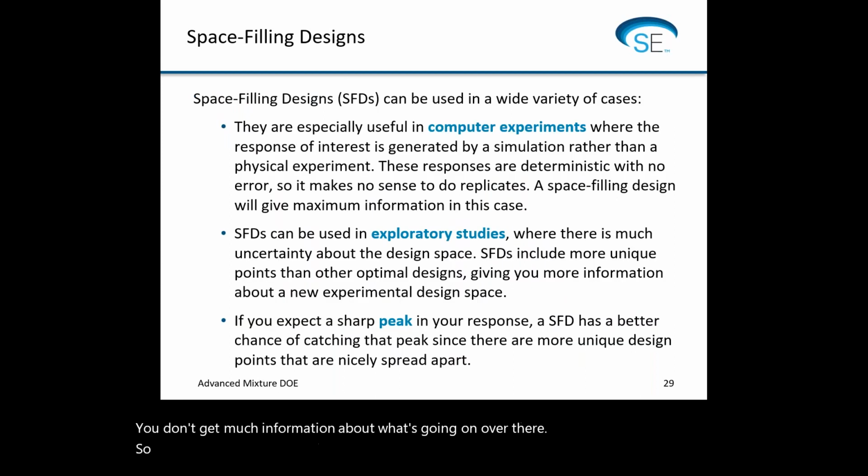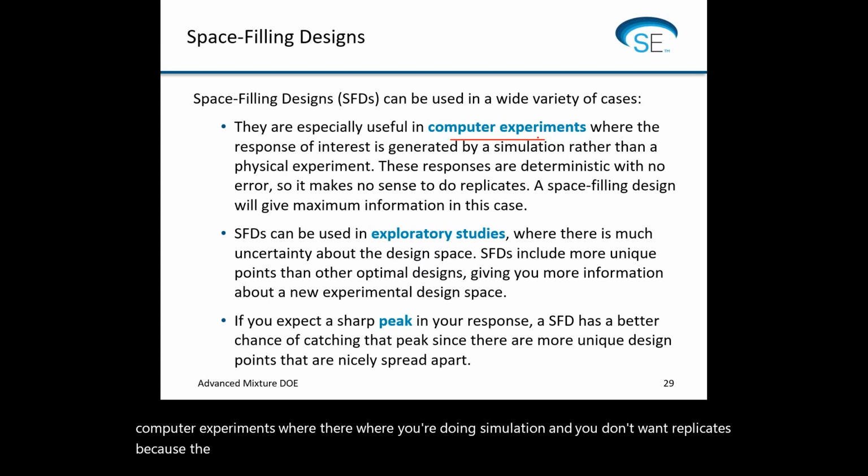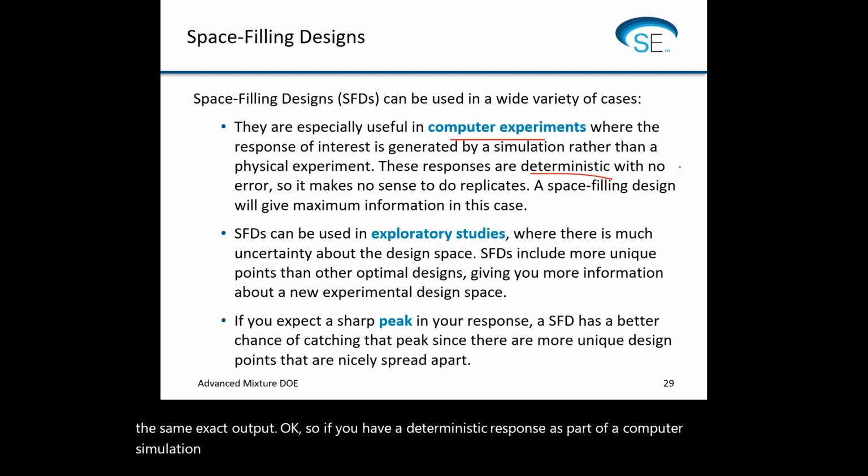So space filling designs can be used in a wide variety of cases. They're very popular in computer experiments where you're doing simulation and you don't want replicates, because the same set of mixture components or factors is going to give you the same exact output. So if you have a deterministic response as part of a computer simulation, don't do replicates. A space filling design is going to give you usually maximum information in that case.